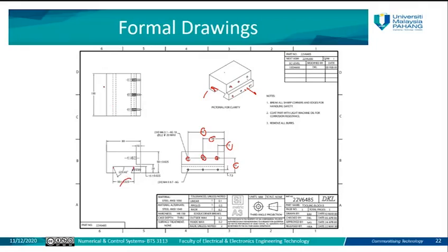For the top view, you have here 100. This is one of the dimensions, which represents the length of this line, which is 100. And from the other view, you can find the length of this extra line. So this information will be extracted from the drawings. Later on, you are going to see how you can use this information to write the program, or to guide the machine spindle or machine head to move on top of the product, to create this product and to come out with a real product at the end of the process.